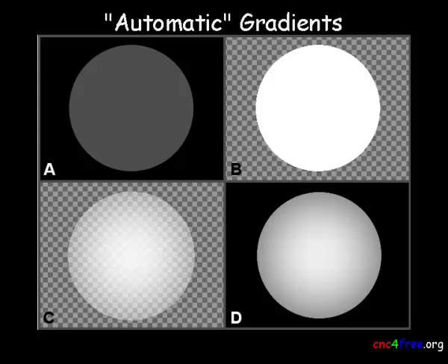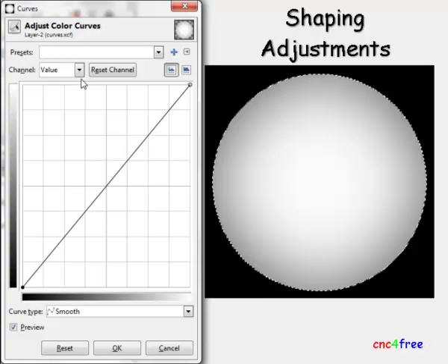In View D, both layers are visible. The maximum height shape on the transparent layer overlays the minimum height base layer. The combined result is a height map gradient that will deform a mesh surface or tool path. Shaping applied by the gradient is controllable. A bitmap is used for this example, but the same principle applies in work with vectors.